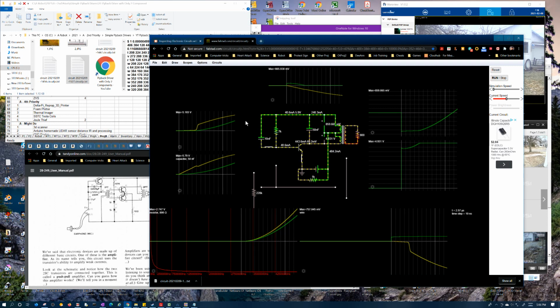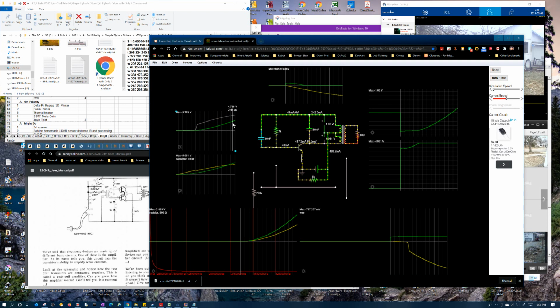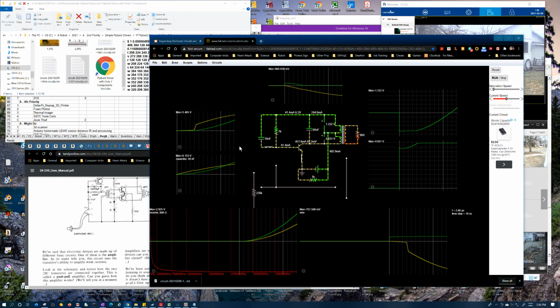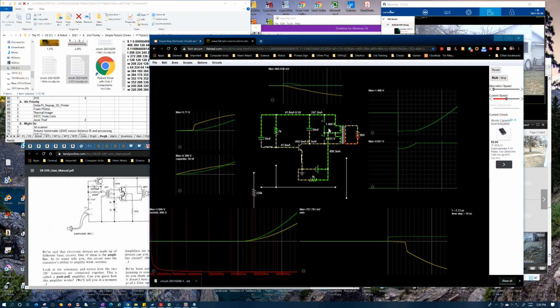See, as we do, voltage is really starting to be impressed across these capacitors. So this has already got like 6 volts across it, because this voltage here is being added on top of this voltage here, so it's causing these capacitors to charge above the 5 volts of the battery.